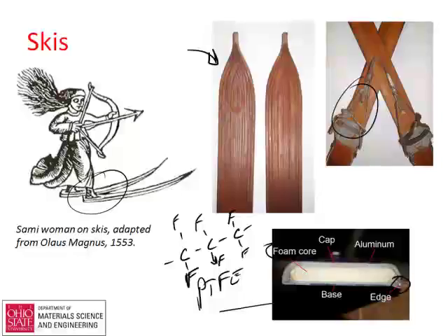And foams are really important. The function of the foam is it adds minimal mass, but it does provide some connection between the cap and the base. If you can keep these connected, but keep them a fair distance from one another, we end up seeing something that's actually very, very stiff, and we can control these properties by controlling this thickness.